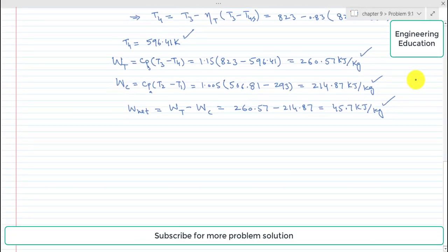So generator work is equal to mechanical efficiency into net work. So we now here incorporate the drive efficiency or the mechanical efficiency, and it is 97%, and the net work is 45.7.